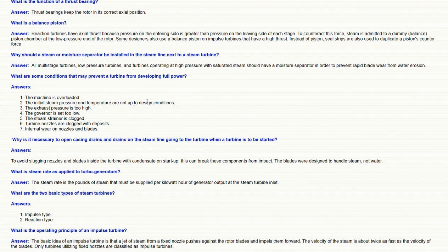If exhaust pressure is high, it means we are losing power, we have lost our energy, which we have to convert in the steam section areas in the blades. So our main concept is we have to convert maximum enthalpy, maximum internal energy of the steam into mechanical energy at the steam section blade areas.